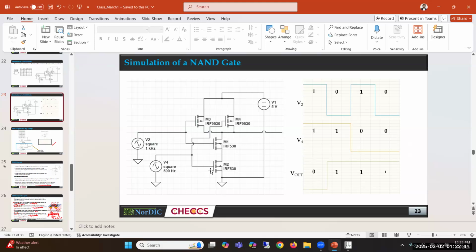So now you will do that actually. I will not show you the physical design anymore. I'll just remind you the steps. In NAND, we have two PMOS connected in parallel and two NMOS connected in series. So you'll have to bring two PMOS layouts from the MOS generator, and two NMOS from the MOS generator.